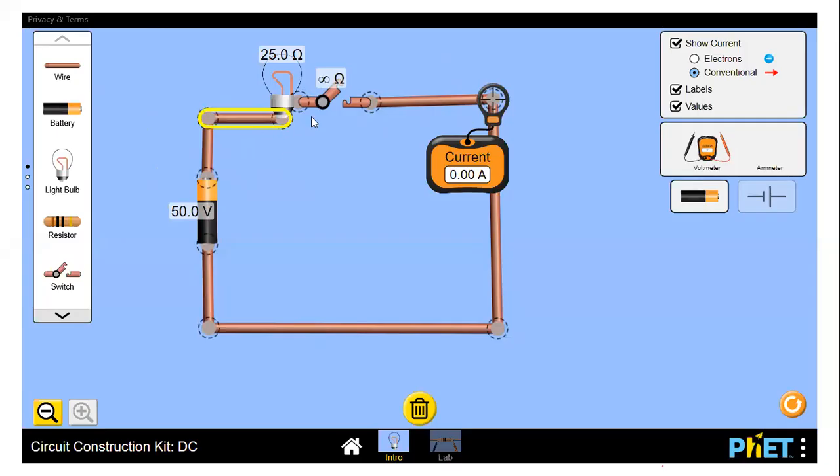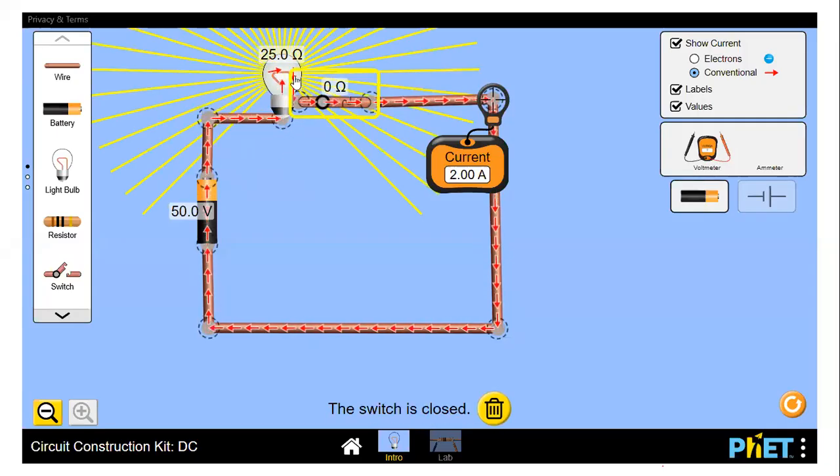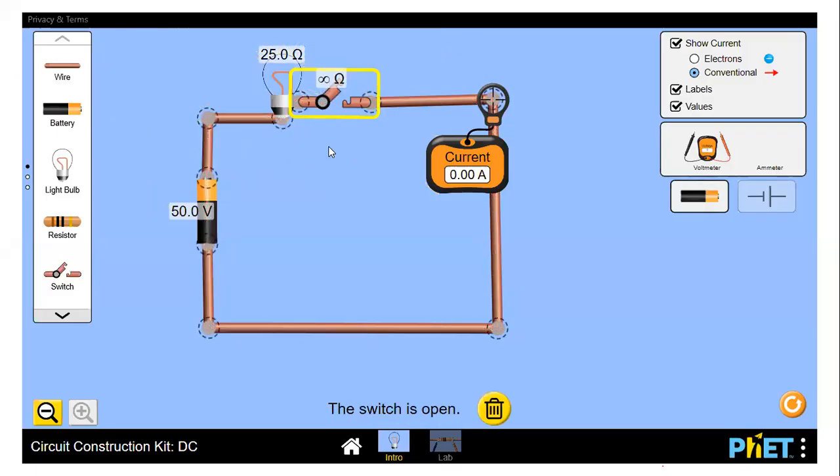But what if you want to replace this lamp with another lamp? Even though this switch is off, you will receive the voltage till this end. And if you accidentally touch this point, you will receive a shock, right?